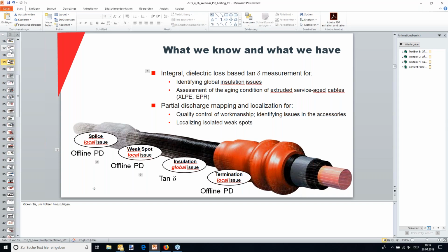So Robert, this is a good opportunity. This questioner asked about what is the IEEE or any other standard for this test? Does the standard specify the PD value for service cable and new cable, service stage versus new? I know we talk about IEC often, but given most of the audience is IEEE, it's a good opportunity to make this clarification. In IEEE, there is a separate chapter on that, which is IEEE 400.4 for the damped AC.